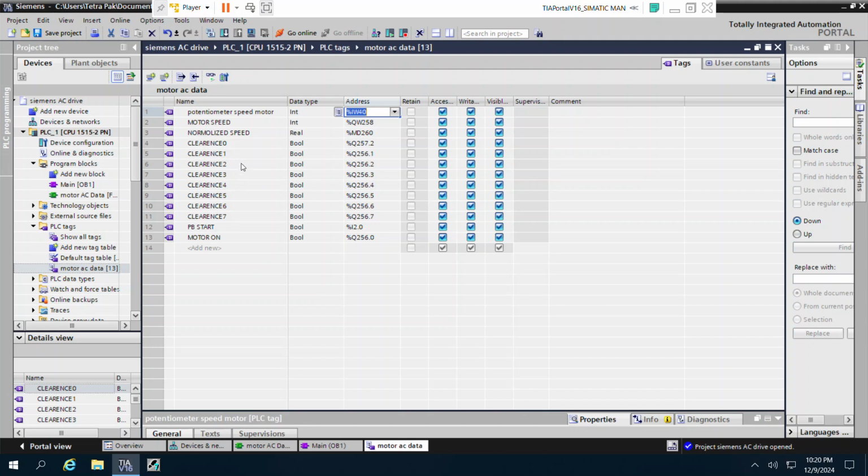The AC drive of Siemens has 8 inputs, we can say a byte, 8 bits. We should activate them always to let the AC drive run automatically when the power is on. I will show you how to do this.